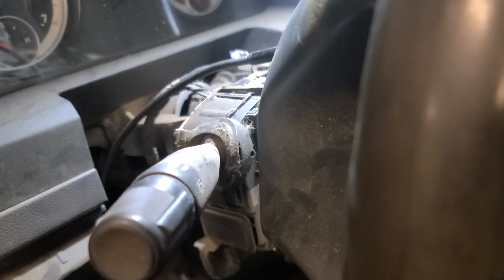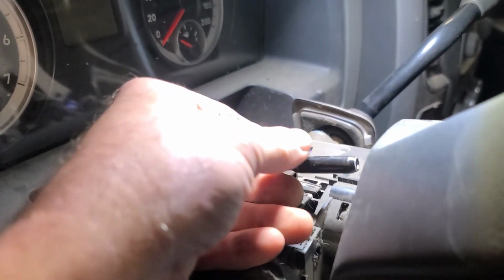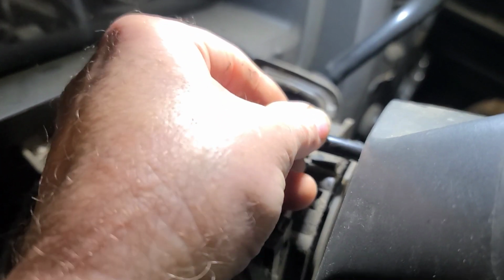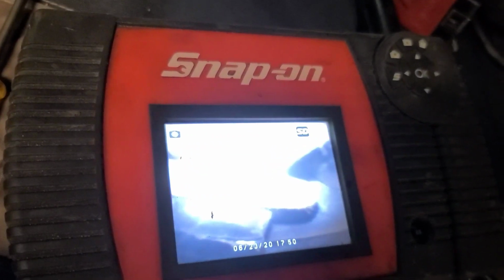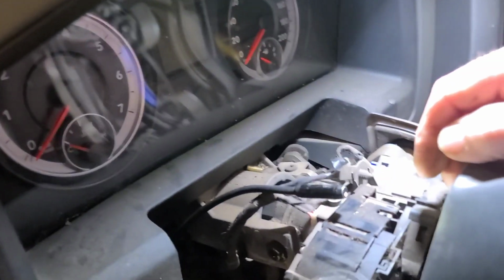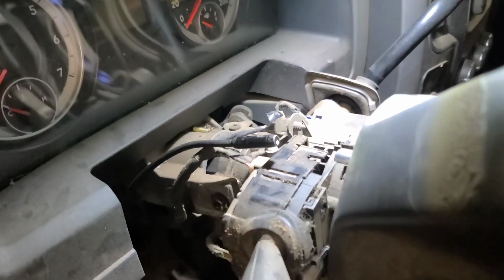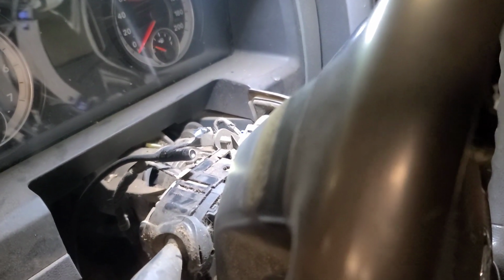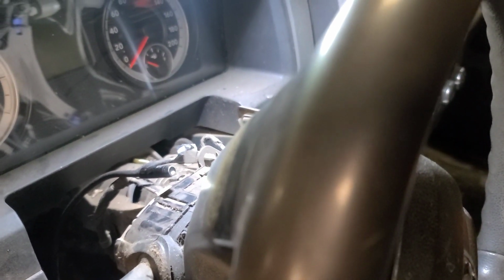So once you get the steering column covers off, you can access the 3 releases. Let's see, there they are there, looking at them with the borescope. It's hard to see. Got a little wire there. So there's one at 10 o'clock, 2 o'clock, and 6 o'clock. So you have to turn the wheel so that the 10 o'clock position is at 12. And then you have to go in there. They show it's a special little hook tool, like a small screwdriver.